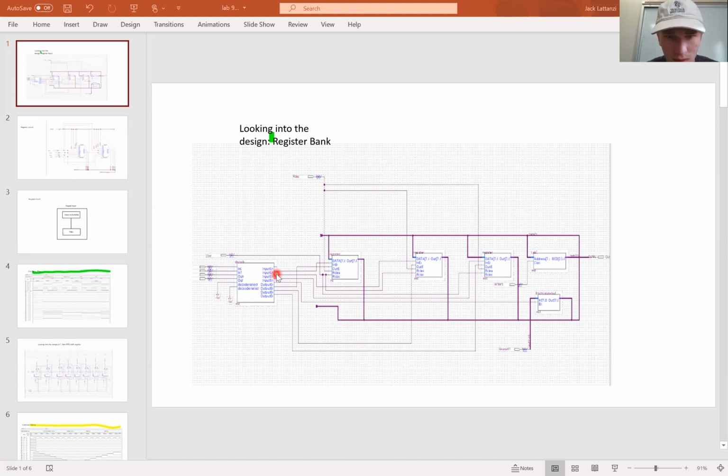So the way the circuit works is the register has a value entered into the keypad, which is down here, which I'll explain later. It goes through the buses. If the input value is, say, 0, 1, then from this connection the input for this first register will be enabled, or register 1, which is here.